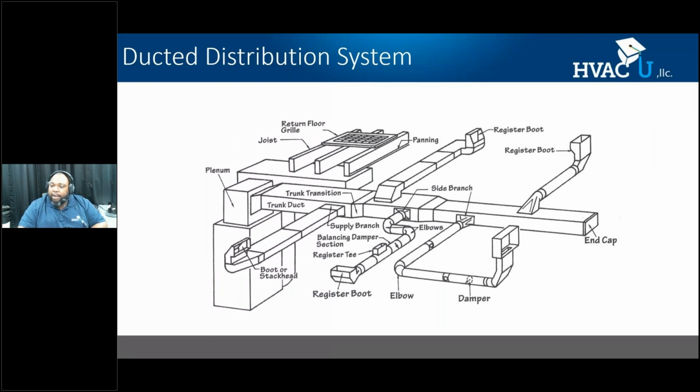There's other arrangements, but for the most part, this is what the ducted system will look like. All right, now, as a contractor, I've seen over many years in different markets a bad habit that the HVAC industry has gotten into, and it depends on your area, where a load calculation was not performed and equipment was replaced with the same size. All right? And there was never any attention to the duct system. Now, the purpose of the duct system is to get the conditioned air from my equipment, whether heating or cooling, to the different parts of my building efficiently. If the duct system is not sized and designed appropriately, I will fail at that.